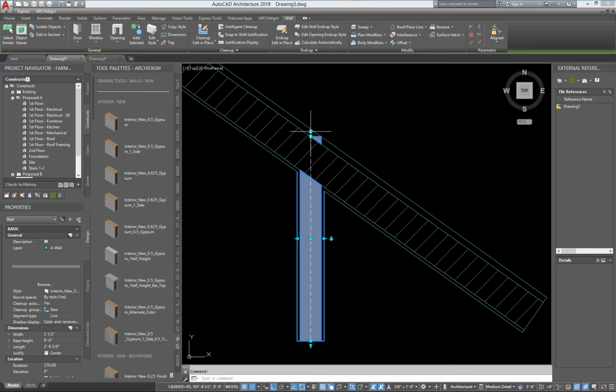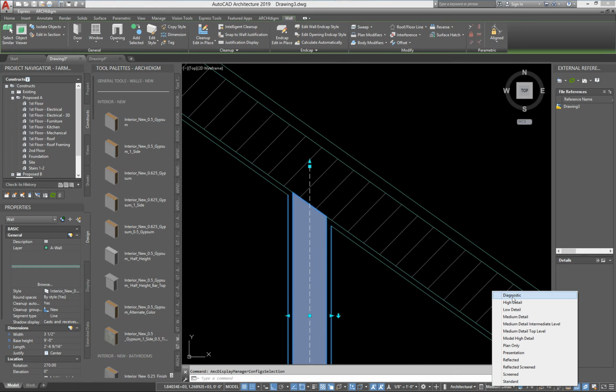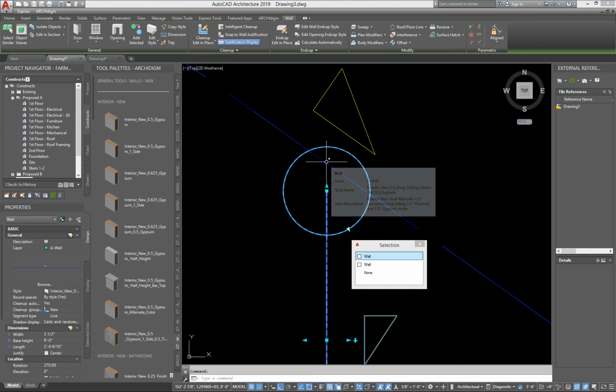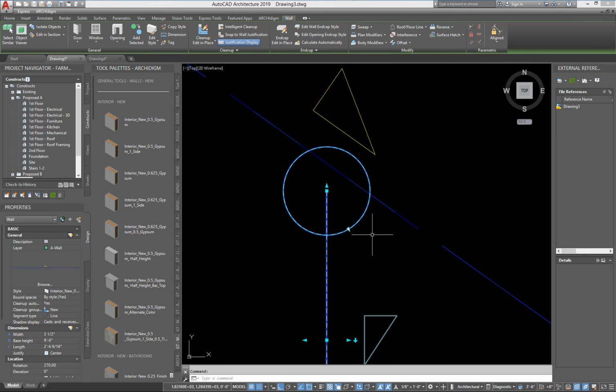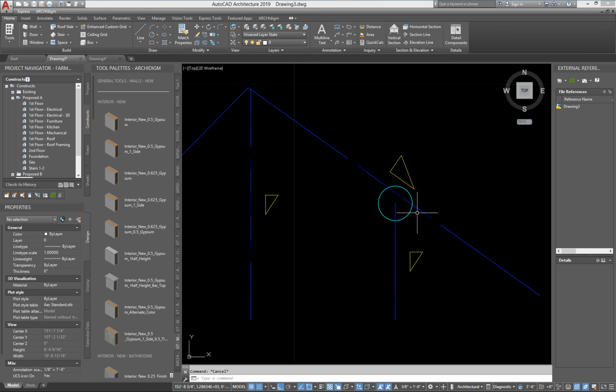Okay, now what I'm going to do here is pull this wall back a little bit, and then that fixes it. Why does it fix it? We'll go back to diagnostic, and you'll see because the cleanup circle is now reaching out far enough to hit the other baseline. All right, so you could do variations of this, more or less, of the cleanup radius.